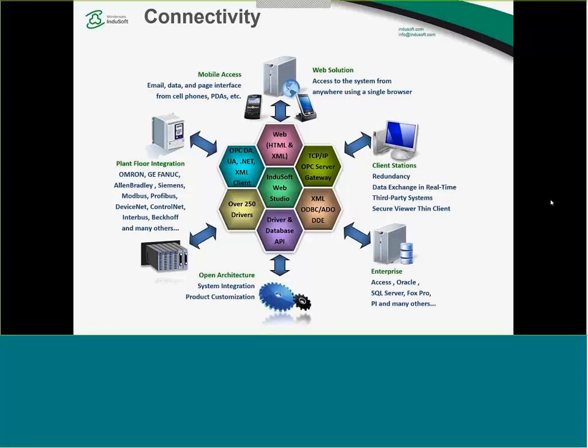Nowadays InduSoft Web Studio has more than 250 native drivers, from proprietary protocols like Omron, Allen-Bradley, and Siemens, to industry protocols like Modbus, Profibus, DeviceNet. So out of the box, you have all the drivers that you need to talk to all the industrial devices you might have in your plants, in your process.